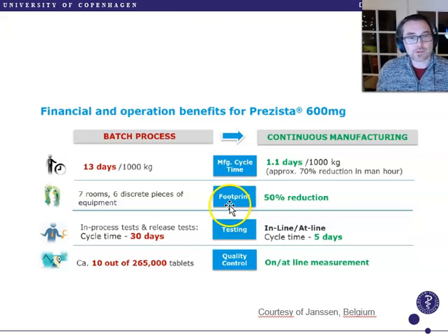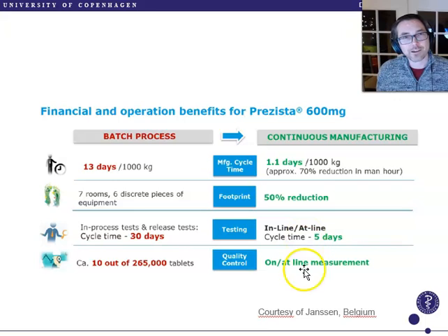This all requires implementation of process analytical technologies, but once you have this up and running, these process measurements allow for reducing the cycle time of a given batch from 30 days to 5 single days. And once you have these process analytical technologies there, you can have good analytical possibilities for doing online and at-line measurements from moving material, and by this means increasing the sampling frequency.